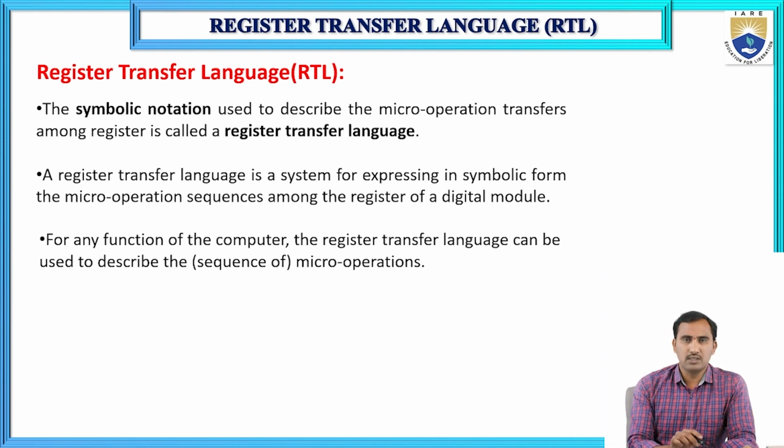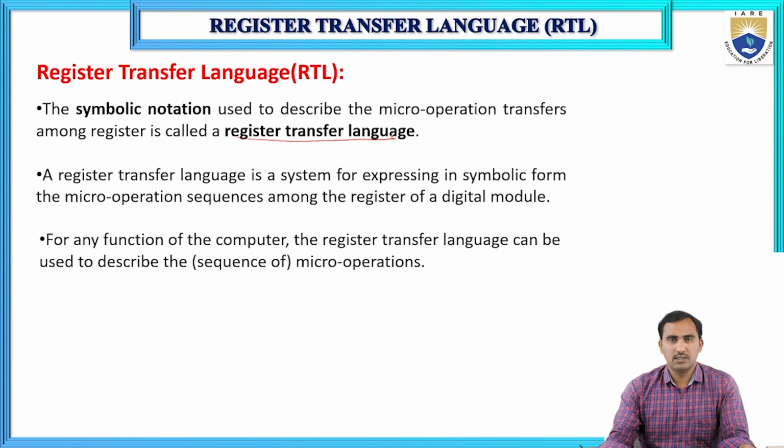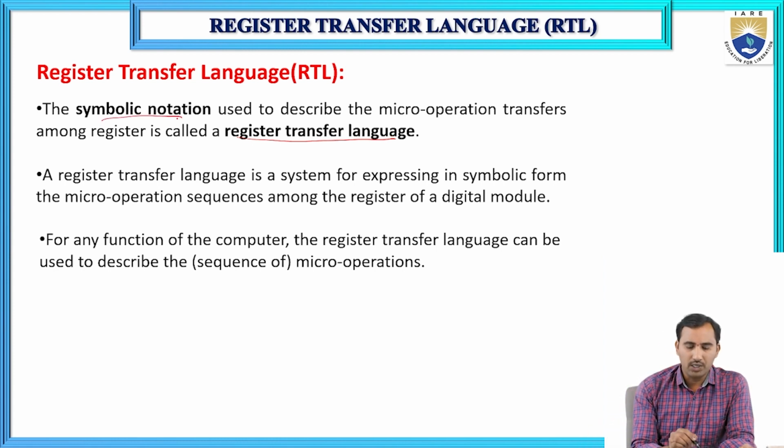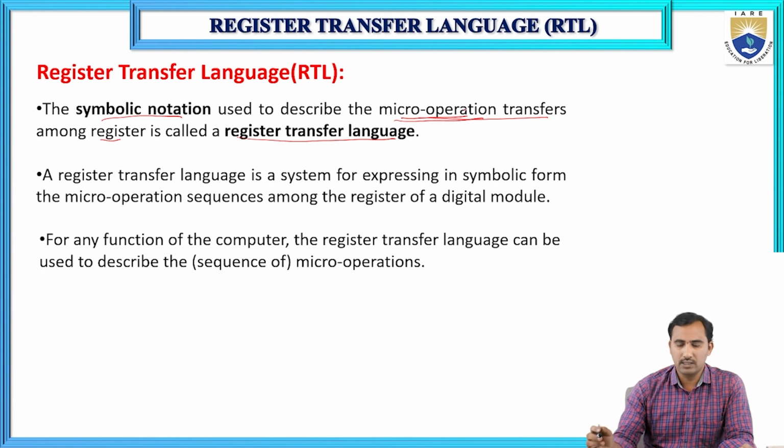Register transfer language is a symbolic notation used to describe the micro operation transfers among registers. Using this symbolic notation, we describe the micro operation transfers among the registers. A micro operation is the operation that we perform on the data stored in registers.